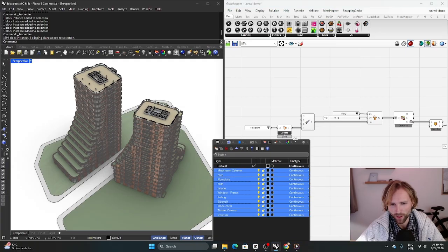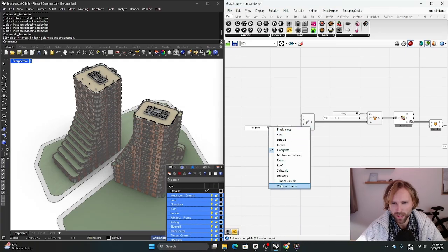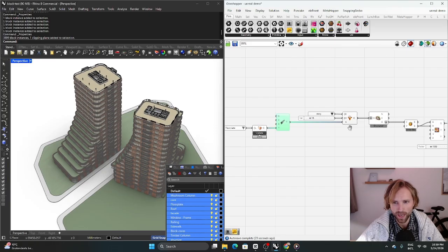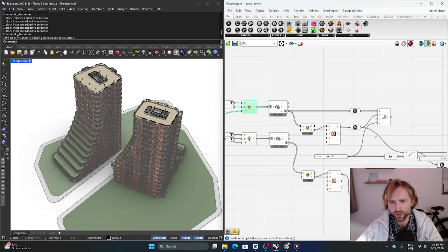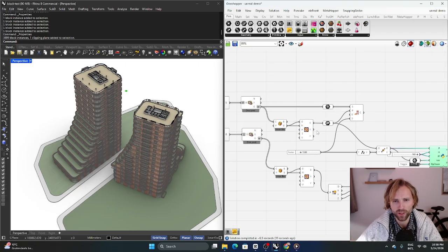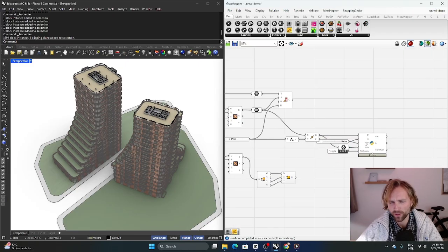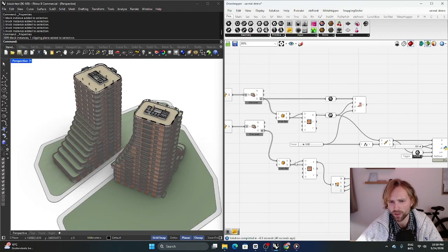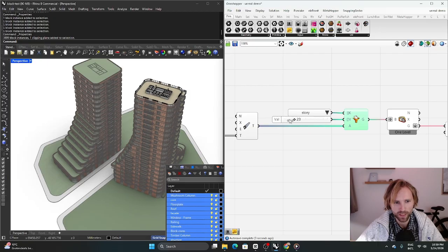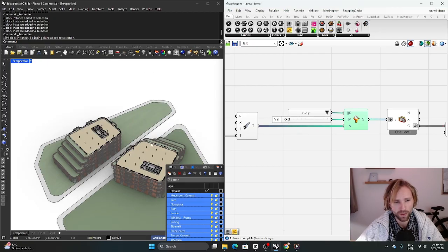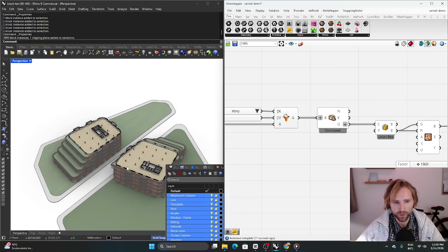All right, now this flow I really love. So essentially we can query one of these layers, right? So now I'm going for a floor plate, and then I'm filtering it by the story. And then we just explode some of the geometry on top of it, and we basically turn it into a section. I wrote a little bit of a Python node, but I believe there's also a plugin that does this for you. So if I just slide this slider for a bit, then I can slide through my building and select the geometry from a given story.